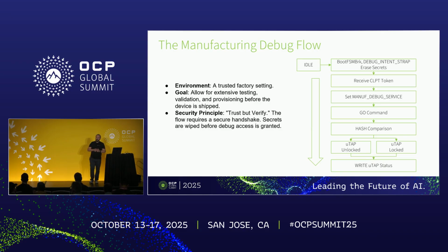During manufacturing, we have a special lifecycle state intended for UDS provisioning. So basically, we disable debug functionality in core and MCU so that we can provision UDS secrets in a secure manner without giving attackers the ability to extract those secrets.